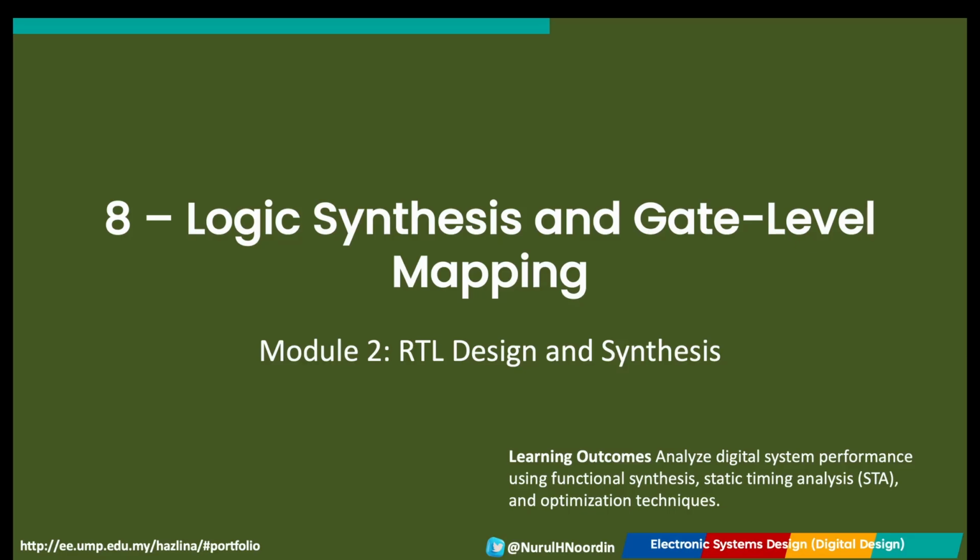Hi, welcome to chapter number 8, Logic Synthesis and Gate Level Mapping. In this chapter, we will look into how abstract RTL Verilog code is transformed into a gate-level netlist and mapped to physical FPGA hardware, focusing on the synthesis flow, optimizations, and the Quartus Prime environment.